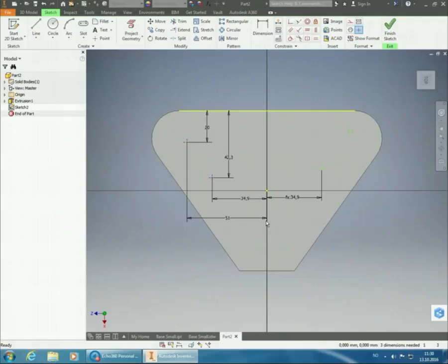And that is because if I click on this one to check what it says, it's supposed to have the exact same dimension as D9. If I had added some sort of math equation to this, then it would put that into context with the dimension of D9. But so long as it just says D9, it's going to be the exact same dimension as D9.